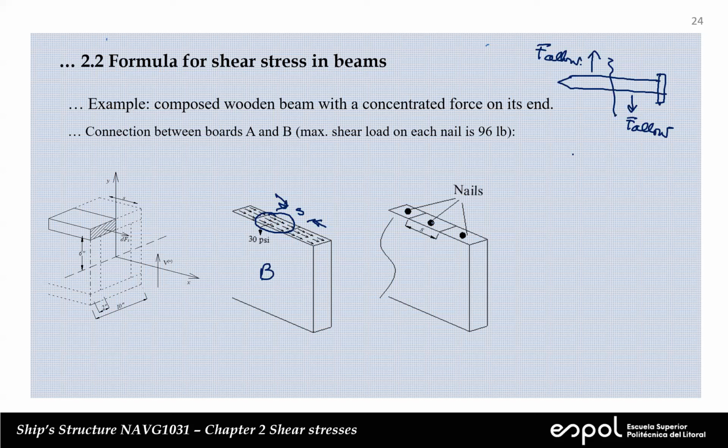That's what we do here. The maximum force that can develop in each nail will be replacing the shear distribution that we originally have. So that's the shear stress times the area. Now S is unknown.